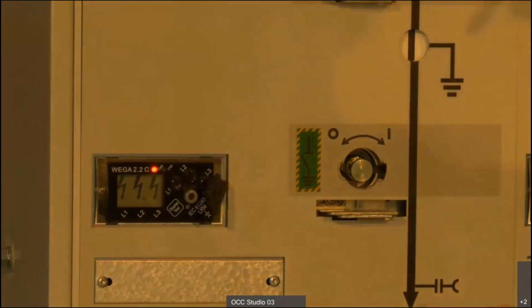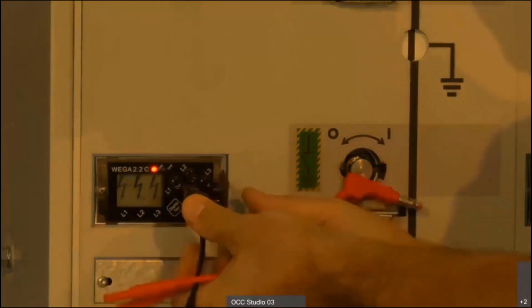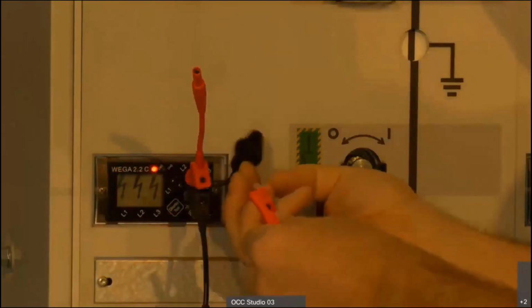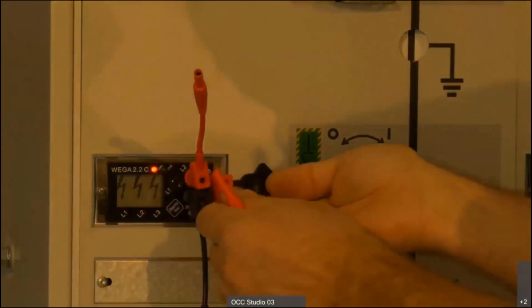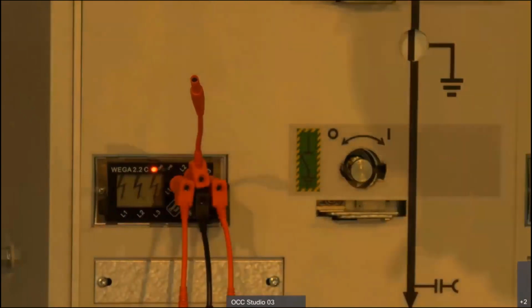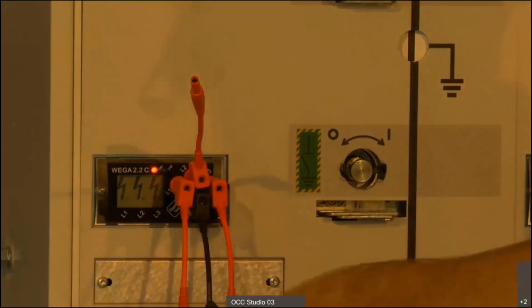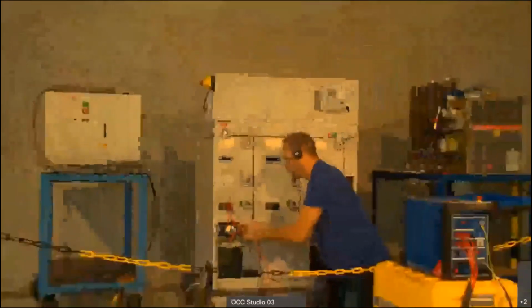With this VTM test, we're providing also the adapters for that, so you can easily connect to them. And it is basically a capacitance which is measuring the voltage on the primaries. So we have very low signals. If the breaker is a 24 kV breaker, which means usually you have 10 volts or up to 30 volts coming out here. But because we have not so much voltage, it's enough to show how it looks like.